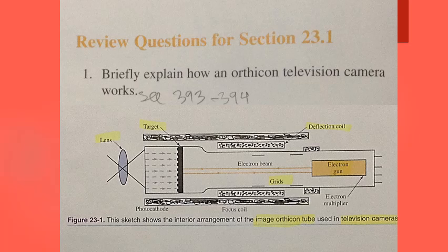Further, the scene in front of the camera focuses on the photocathode. Through a standard camera lens, the varying degrees of light cause electrons to be emitted on the target side of the cathode. These form an electronic image of the scene. The target plate operates at a high positive potential. The electrons from the cathode are attracted to the target. The target is made of low resistance glass and has a transparency effect. The electron image appears on both sides of the target plate.